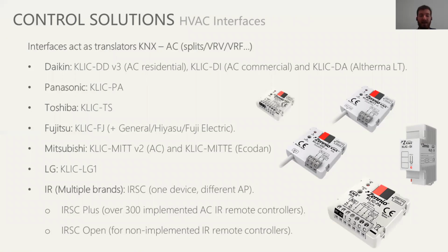But an interface is just translating the orders. It's not producing a relay change. It's not operating a relay to say open the valve, close the valve, or turn on the fan speed at medium level or at maximum level. An interface is doing something different. An interface is translating from KNX to the Daikin language, the Panasonic language, the Toshiba language, whoever that is.